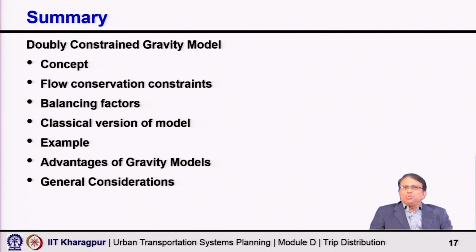So, what we discussed in this lecture is the F_ij calibration and the role of the zone to zone or socioeconomic adjustment factor, which accounts for something beyond the deterrence due to time or cost, likely due to socioeconomic composition.